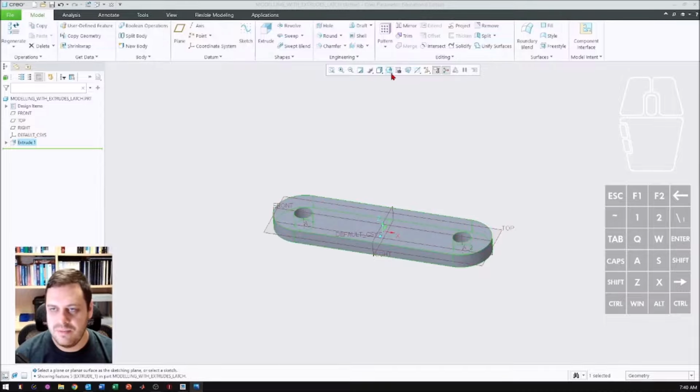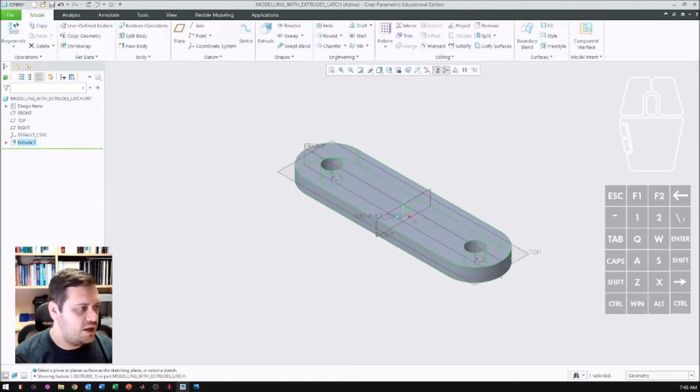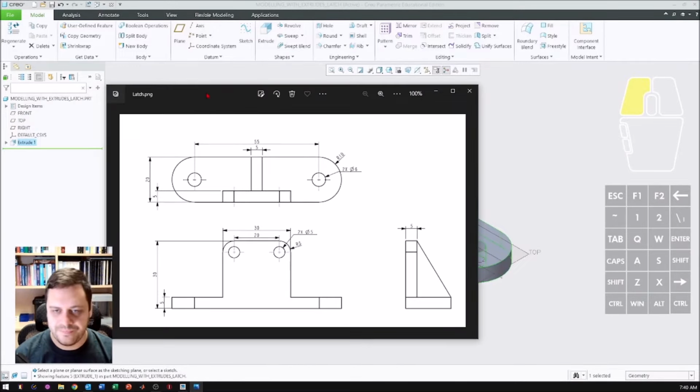One thing to keep in mind is you want the best orientation for your object. To do this, if you drop down in this menu through here, which is just the view menu, we want to go to isometric. The reason I've done this is I essentially want to show this gusset section in an isometric view, and this comes down to your axonometric views. You want to have as minimal views as possible. So to make it a little bit easier, I'm going to let CREO do the work here.